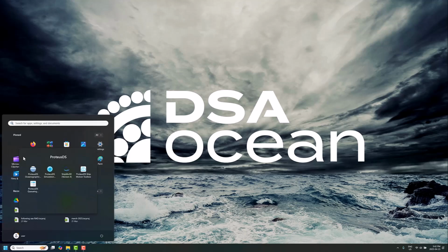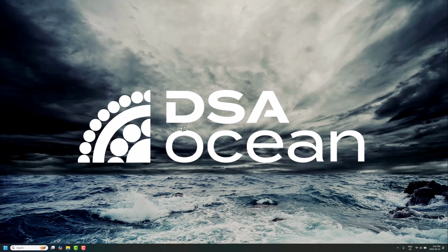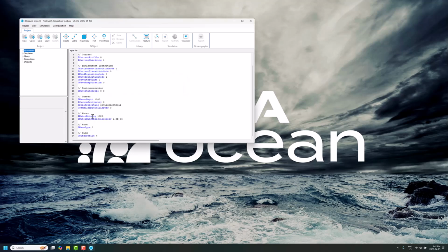Well, when we look at Simulation Toolbox, a lot of the default sea state options, the wave types, you have sinusoidal waves, Airy waves, you've got a couple of different spectrums, JONSWAP, Pierson-Moskowitz, and custom spectrums, and so on. But sometimes when you're looking at real data from a deployment or an actual project, you'll see some really complicated combined spectrums where there's a swell that's going one direction and then a wind-driven, messy, choppy sea that's totally different frequencies going a completely different direction.